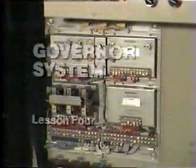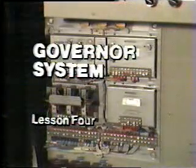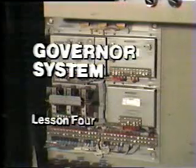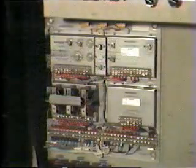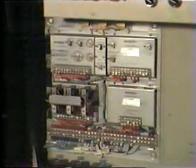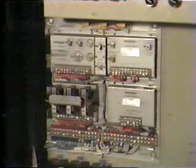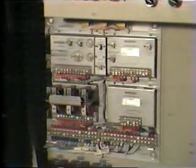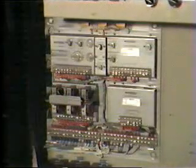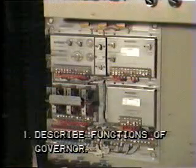Lesson 4, Governor System. The governor system is used to control the speed of the engine during varying generator load conditions. The governor senses engine speed and kilowatt load and sends signals to the servo actuator to make appropriate changes in the fuel flow. When you have finished this lesson, demonstrate your understanding of the material by taking the progress check on the following objectives.